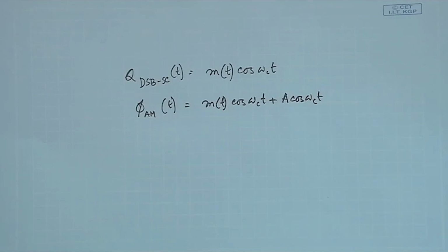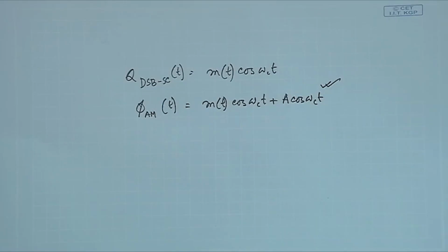and we have seen the relative benefit of it. So here in AM we have seen the receiver becomes very simple. It's just an envelope detector, whichever way you do that. We have already discussed two methods of envelope detection, and for DSBSC we need to generate a local carrier. So for that we need to extract the carrier from the incoming signal. That requires carrier synchronization and all those things. Demodulation of DSBSC was very simple. You have to again remultiply with cos omega ct followed by a low pass filter. This is something we have already discussed.